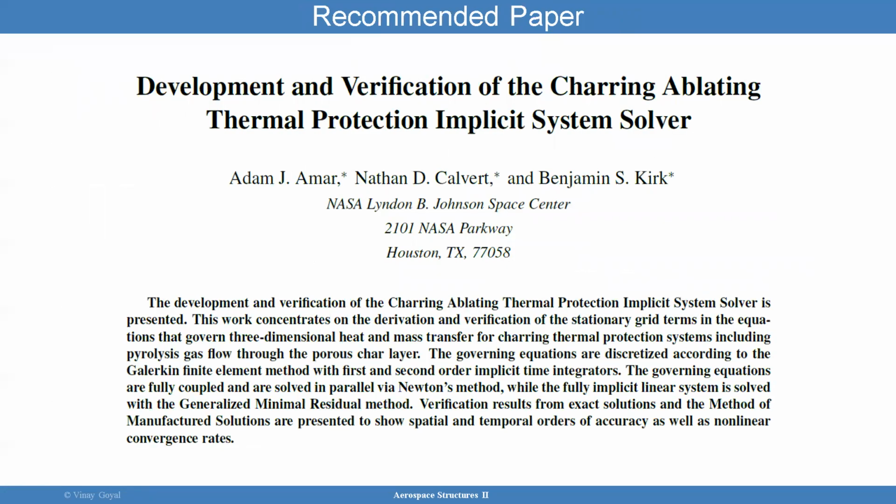I really recommend reading this paper. It's called Development and Verification of the Charring and Ablating Thermal Protection System Implicit System Solver. I do think this paper goes into extensive derivations for and verification of what they use for the equations for modeling the heat and mass transfer in 3D for charring thermal protection system, including how to model pyrolysis.